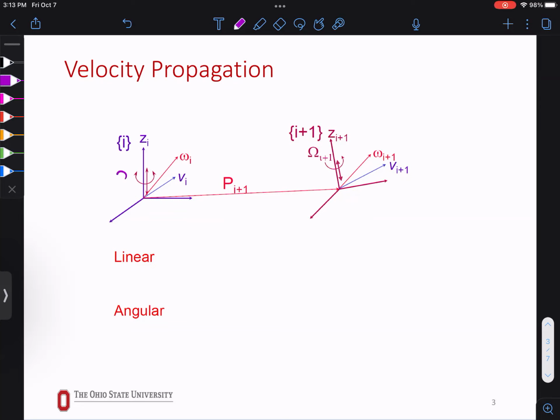So for this one, let's say this is my first joint. Theta dot is the angular velocity, correct? If this was an R joint, theta would be the angular position, and then theta dot is the angular velocity. This joint could also be a prismatic joint, right? Because we don't know what the joint is. So for this method, we will establish the equation for a general case, and then we're going to say, okay, now this is a rotary joint, it will look like this. If it's a prismatic joint, it will look like this. So you need to remember the equation one time.